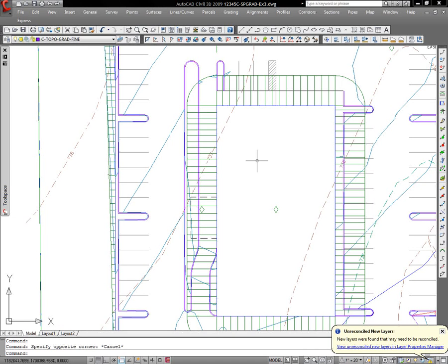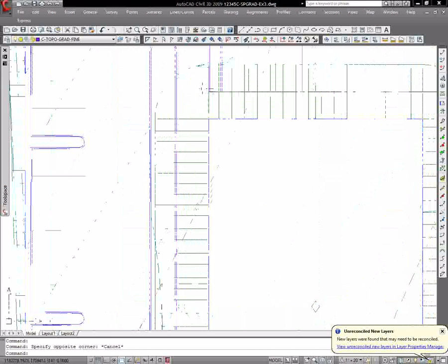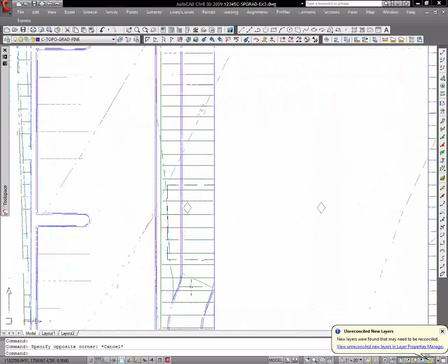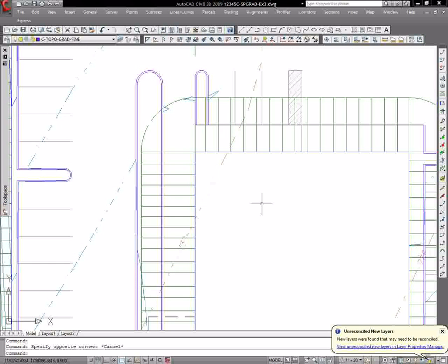Now to take care of a couple of other fine grading issues. One is, if you think about the curb elevations here and then along the building and then down to here, we've got somewhat of a discrepancy. The entire set of feature lines, including the purple curb feature lines and the building feature line, were all set to that common surface called intermediate grading.